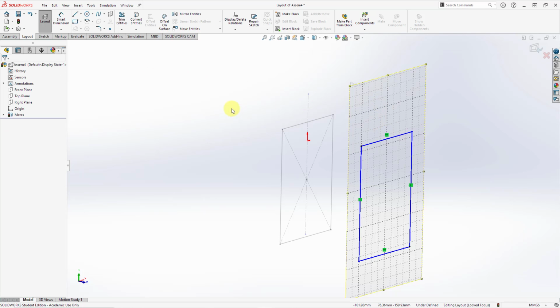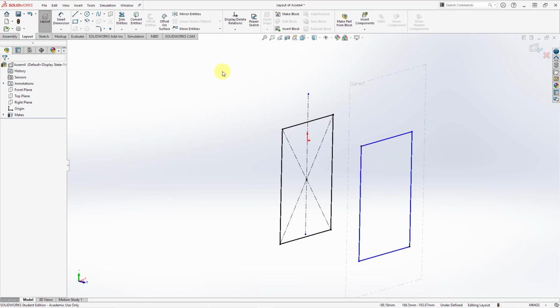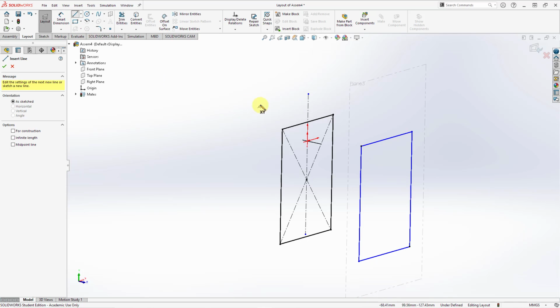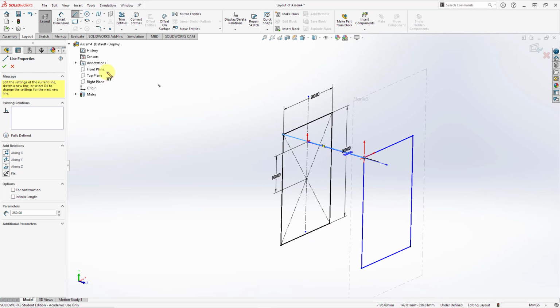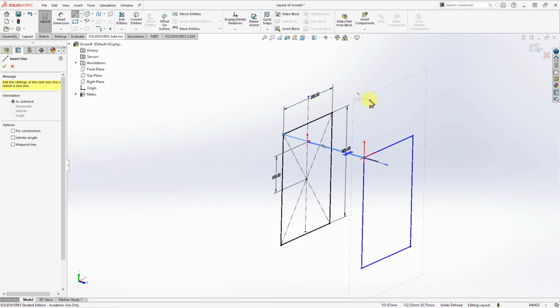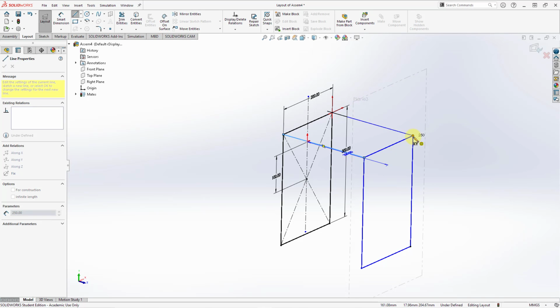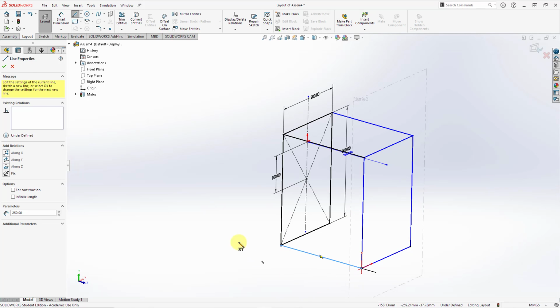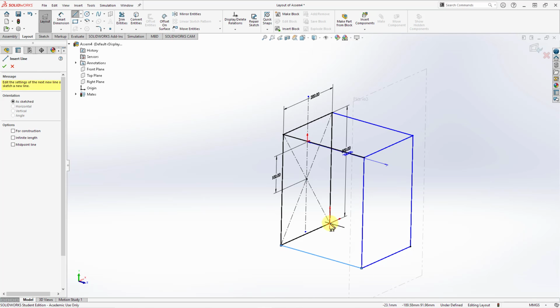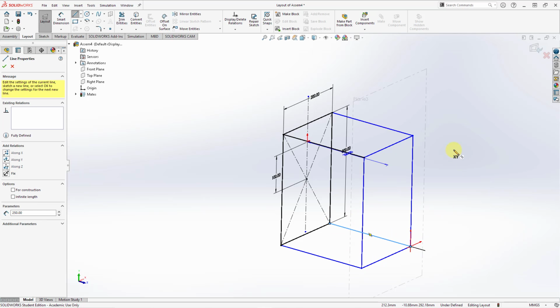To deactivate the plane that you're sketching on, you can double click on the background. And now when I go to sketch different lines, I can click on here and you can then snap it into other different entities. And so that way we're creating, again, our sketch in 3D. That's good for that line. Let's create one for the other different corners in here. And I'm using these in order to represent the box for the case. And let's grab it over there and one other line over here.